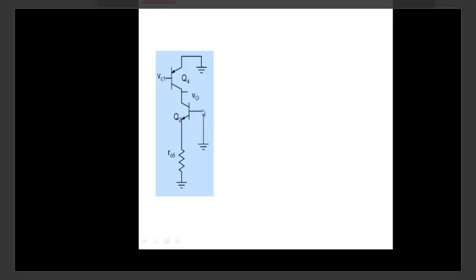So as we said, the gain of this amplifier will be GM4, because this is where I'm applying the input. So GM4 multiplied by, at this particular node, the resistance looking up, R up, and the resistance looking down, R down. When I look up into the collector, it is the output resistance of the transistor, R04. And when I look down, I'm again looking down into the collector of Q2, and the resistance is R02 (1 plus GM2 R05). Sorry, it shouldn't be R05. Okay, R05, fine, parallel R pi 2, right?